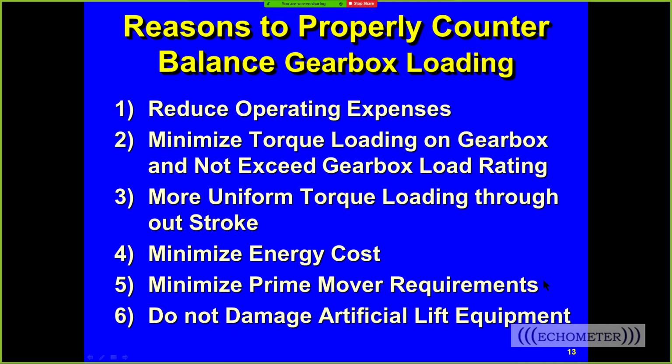Now, when you position the weights and properly counterbalance your unit, you're going to do two things. If it's overloaded, you'll prevent a failure of your gearbox, which will reduce your operating expense. And if you balance it, the percentage change in the cyclic load factor is the same percentage change you'll see in your power bill. So you reduce your power.